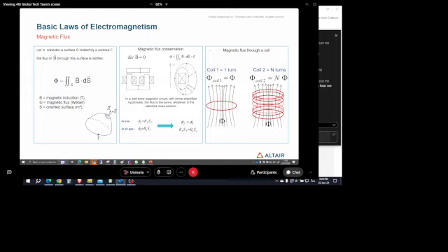But in this example, where we have the coil and it will produce the magnetic flux, the section here is different from the section here. It is mathematically or mechanically possible to understand that the flux density here will be higher than here. And even if we make the air gap, the magnetic flux will continue the movement and move from the north to the south. So there is always this magnetic flux conservation.